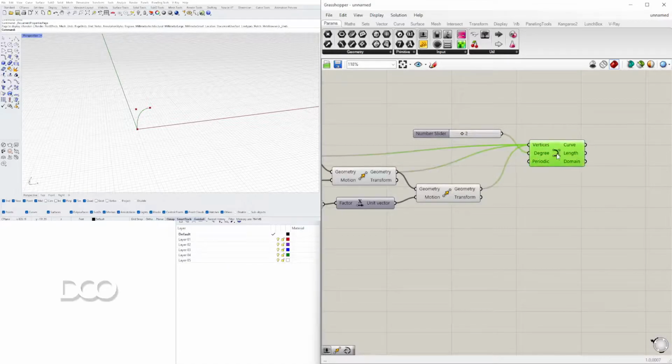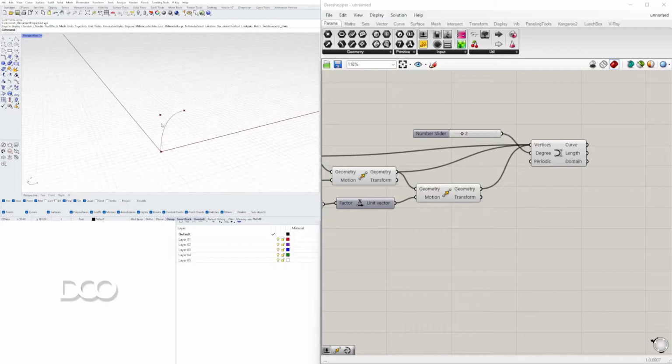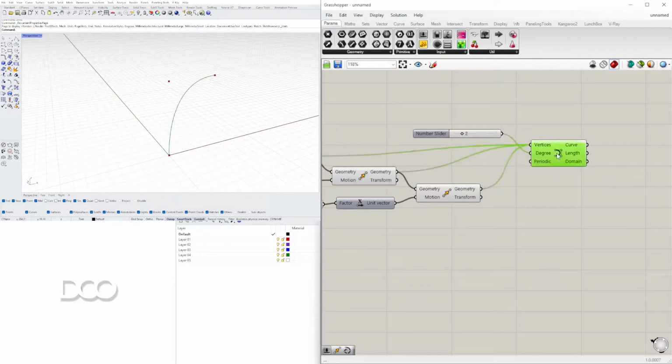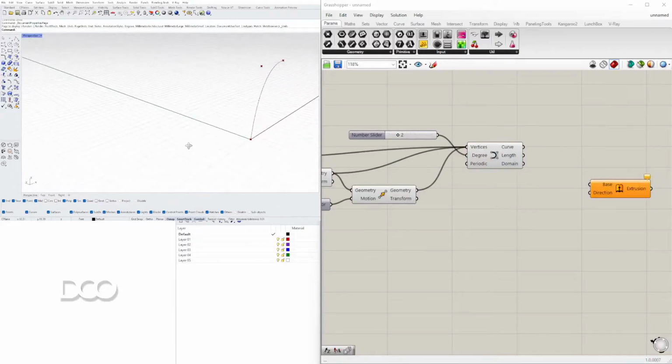This way, the component is running correctly, and when we change it from 2 to 1, it actually changes it into a straight segment. But we do want one whole curve. This way, we can extrude it and have a base surface that we can apply our design to. So let's take our arc and go here to extrude, and we'll be extruding this in the Y direction.